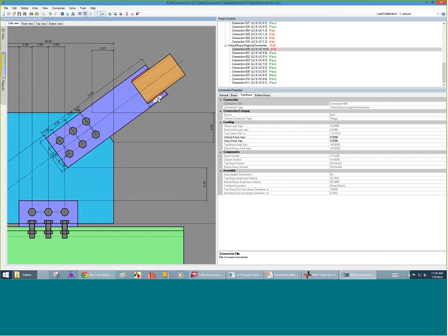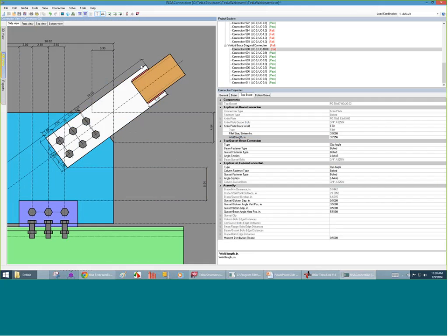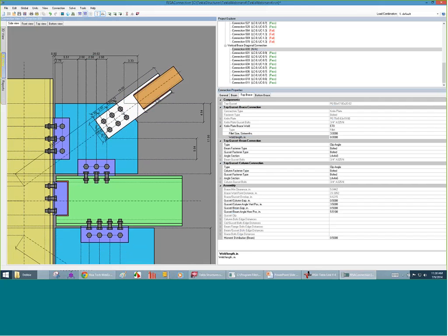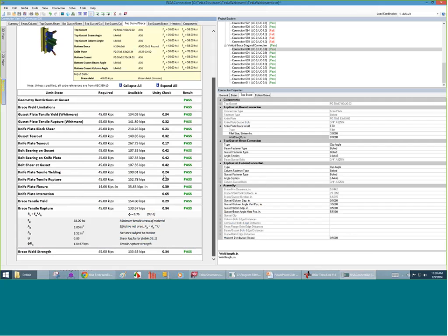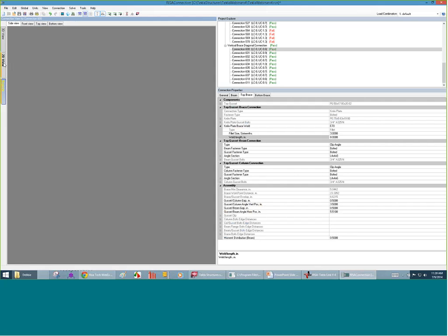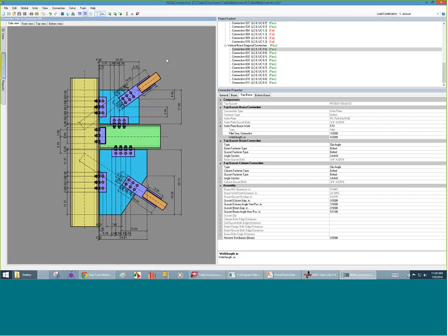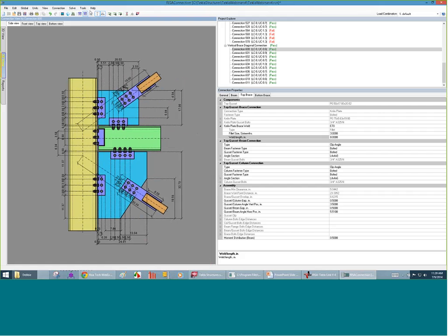So I can pick on that brace there, and make the entire length of that brace, that weld length, longer, and see if we can get that a little more in line. Let's see, actually we can probably continue to grow that a bit. So that's an 8-inch weld now. I moved that brace all the way down real close. I can probably even go a little farther, but let's see how that goes. Run that connection, and then it comes in now in place. So we go back to the reports, and we see now all of a sudden there's no problem. So it's just that I had to grow the tube a little bit farther as I went down the structure.